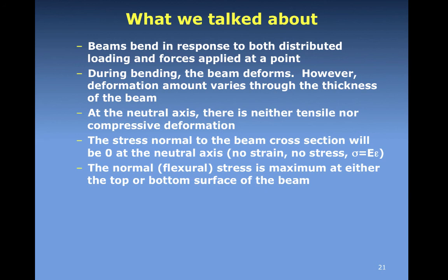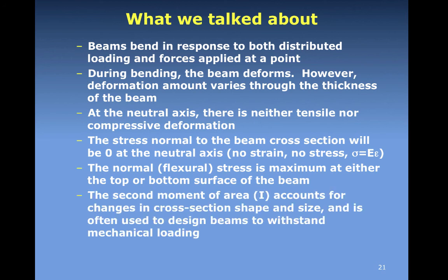Remember too that the flexural stress that we talk about the most and we derive equations for is maximum along the surface of the beam. Depending on the geometry of the beam, which is calculated through the second moment of area, this maximum stress can either be maximum at the top of the beam or at the bottom surface of the beam, and depending on the shape of the beam, could vary considerably between the top and the bottom. For symmetric beams, the maximum stress is equal and opposite in magnitude along the top and the bottom surface of the beam.